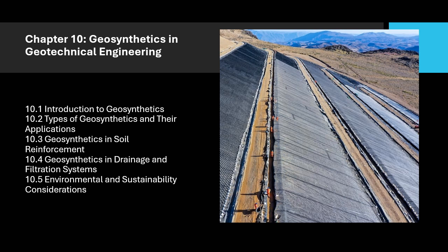Geosynthetics, such as geogrids and geotextiles, are designed to carry tensile forces, thus improving the soil's ability to resist deformation under loading. When these materials are embedded in soil, they act as a tension layer that resists stretching, helping to increase the overall stability of the soil.